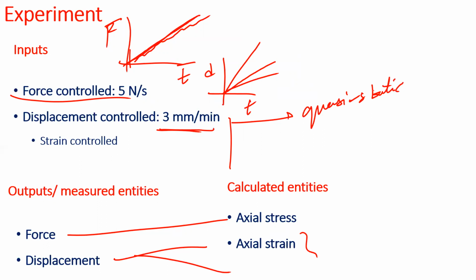This tension test, which we have been talking about all through this lecture, is performed in a quasi-static mode. There is no concept of time. Although we are pulling it, it is pulled at a very slow rate. If I had to pull the sample at 3 meters per minute, that would be a very rapidly stretched sample. That is not the kind of test we want to do while measuring these properties. We are doing it as a slow test. It's quasi-static. You're pulling it slowly.